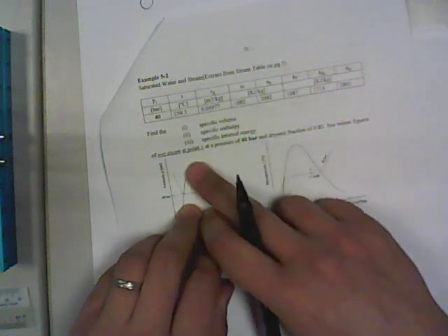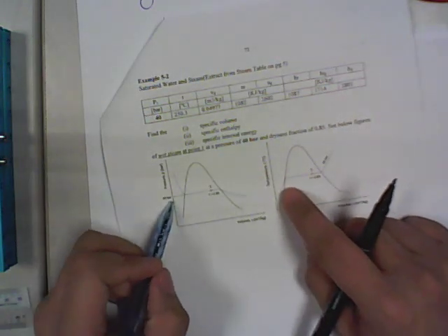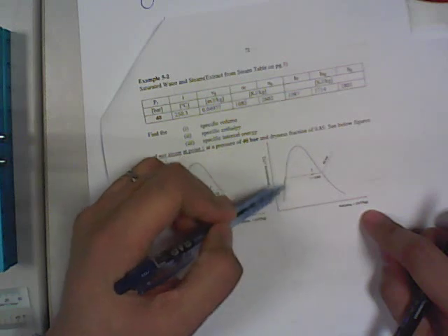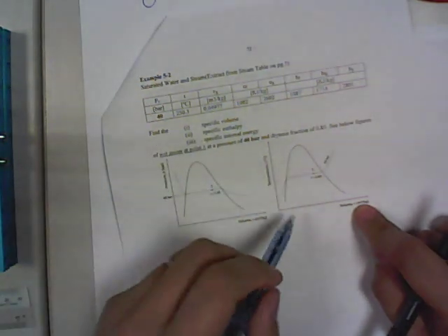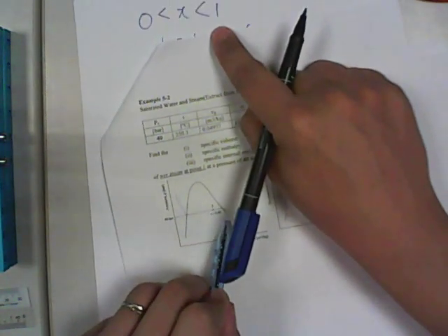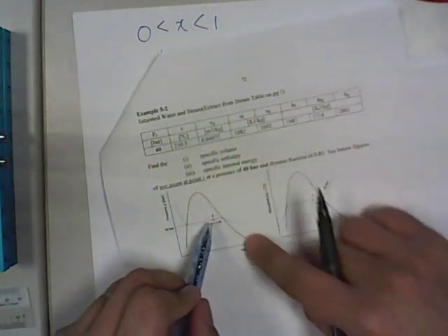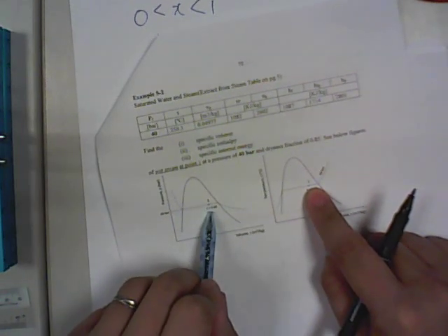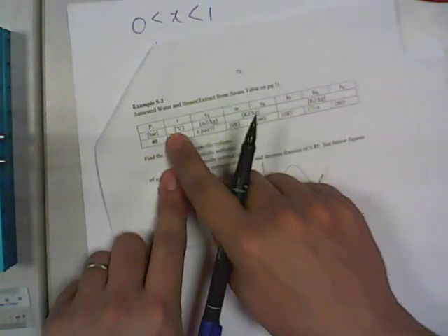So example 5-2, page 72. What you have is that the pressure is 40 bar. So 40 bar is this value on the PV curve, and it is this isobaric line along the TV curve. The dryness fraction is 0.85. Naturally it's closer to the G line because it is closer to 1, right? So we plot it here, similarly on both diagrams. So x is 0.85.